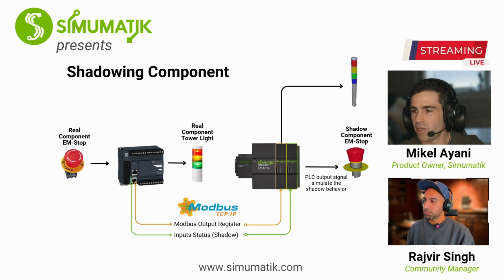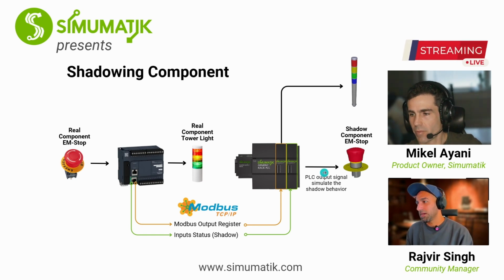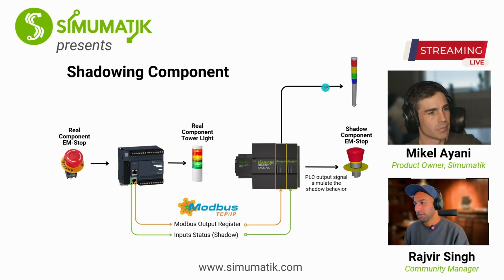From the PLC, we read it into the model as well. Yes, and this output card is just used for shadowing. We don't use it for anything else. And then you see another orange line. This is basically giving the output status of my real PLC. So if I actuate my beacon with a red light in the real PLC, I take the signal out and send it to the first output card, which gives the signal to my beacon in Simumatik, just so that it's not confusing what's happening. So I take an extra card. Basically, this is also kind of a shadow component because it's also just actuating a Boolean signal on and off, showing what is happening on my real device.